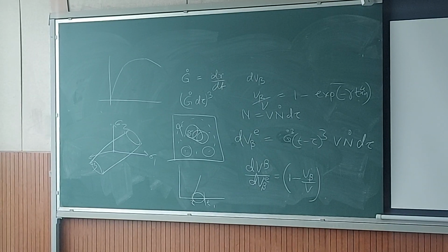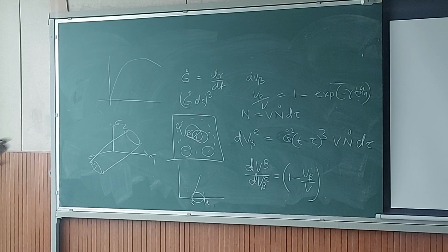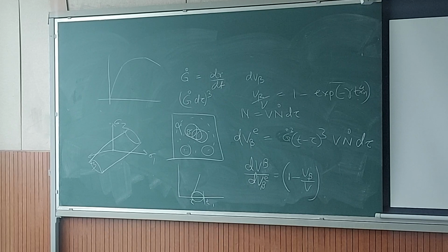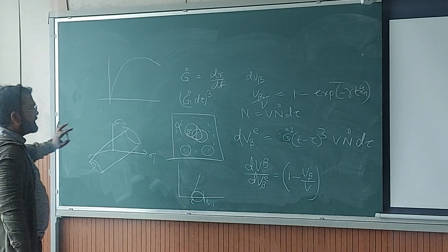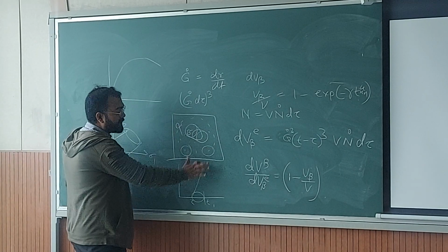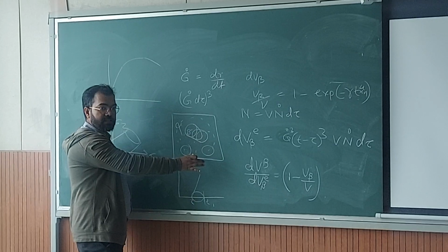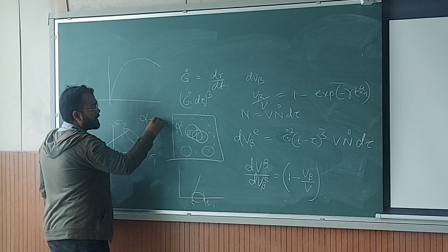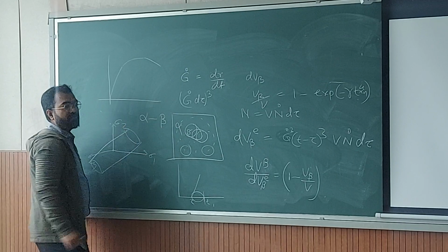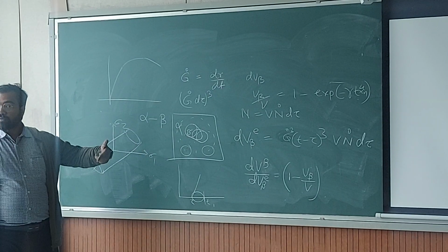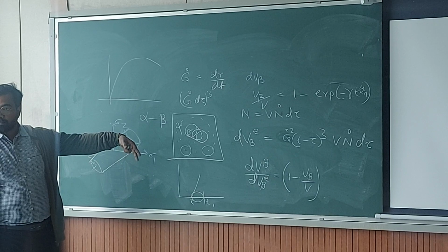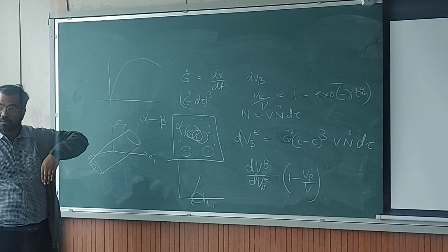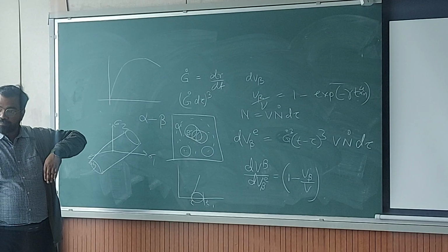after doing the integration. So this is a mathematical model, right? And this mathematical model is telling you that in a parent phase, if a beta phase is precipitating, it can be a complete transformation from alpha to beta, where the final transformed volume is equal to 100%. Okay, so that also can happen when austenite changes completely to ferrite.